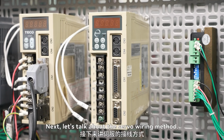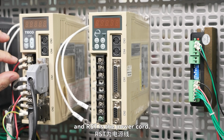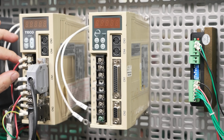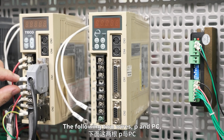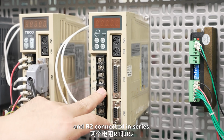Next, let's talk about the servo wiring method. The upper part is the power cord, and RST is the power cord. Generally, there are 2 wires here. The following 2 wires, P and PC, are connected to 2 resistors R1 and R2 connected in series.